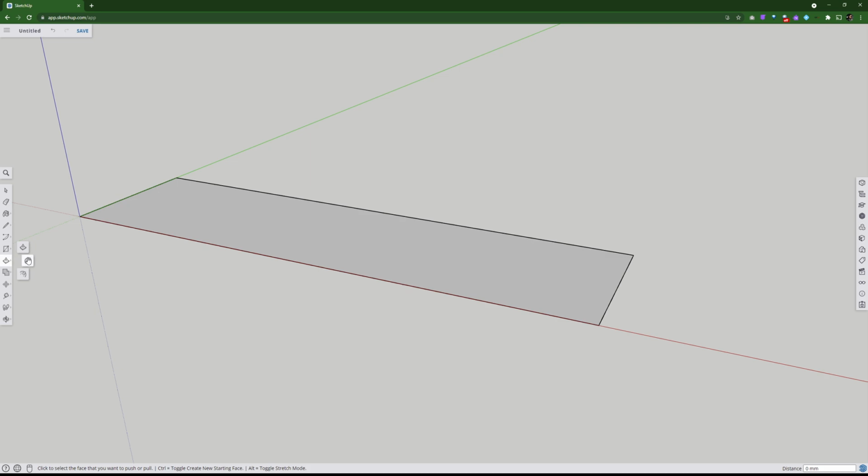I'm going to select push pull. If I had done a revolve, it would have been a revolve. So I have to click on it, change to the tool. So it looks like a little square being pulled up, being extruded up. Okay. Now I'm going to move my mouse along and see how the face of it goes this dotted highlighted pattern. Okay.